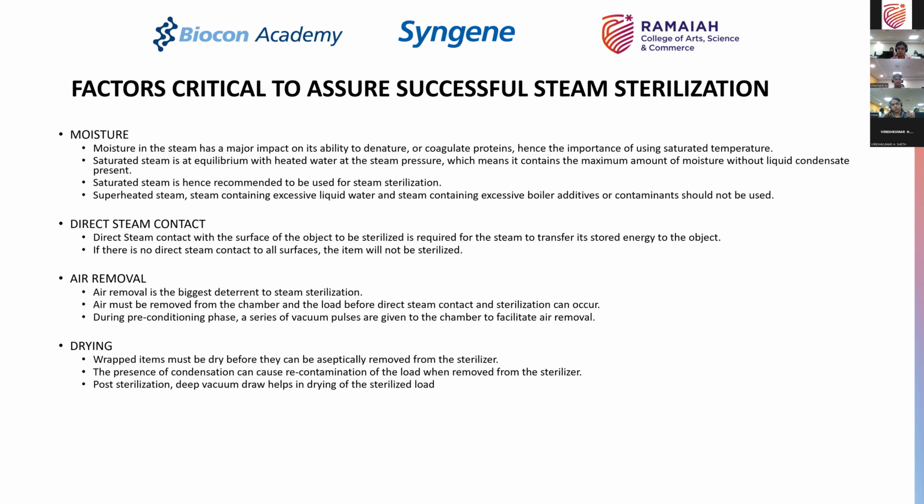Again, the sterilization decision process becomes applicable here also, because when you are doing a sterilization using moist heat, what is the ideal load that you will put inside the autoclave? What is the kind of load that you want can help you determine the type of autoclave that you want. You're clear, I want to use moist heat steam sterilization.